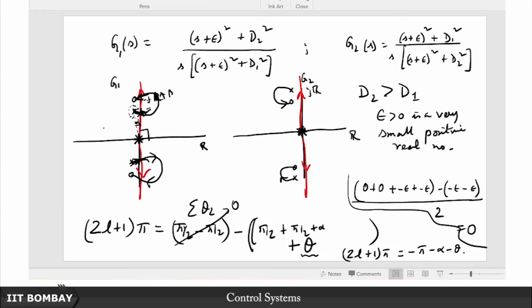Of course, the other thing that needs to change here is this will have all its branches along this. So there will be no asymptote like the one I drew in the earlier case. That was because we were considering this repeated poles at the origin, but now we are no longer considering that. So that kind of completes the picture.